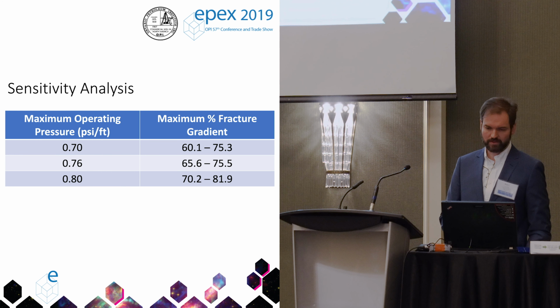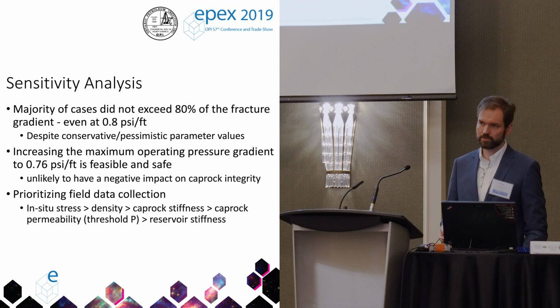Despite data scarcity, running this sensitivity analysis allowed us to conclude that increasing the maximum operating pressure to 0.76 psi per foot is safe and within the limits prescribed in the regulation. And it allows us to prioritize future field data collection efforts for those parameters which have the greatest impact on fracture gradients. But I guess what I want to talk about a bit is how do we automate this process